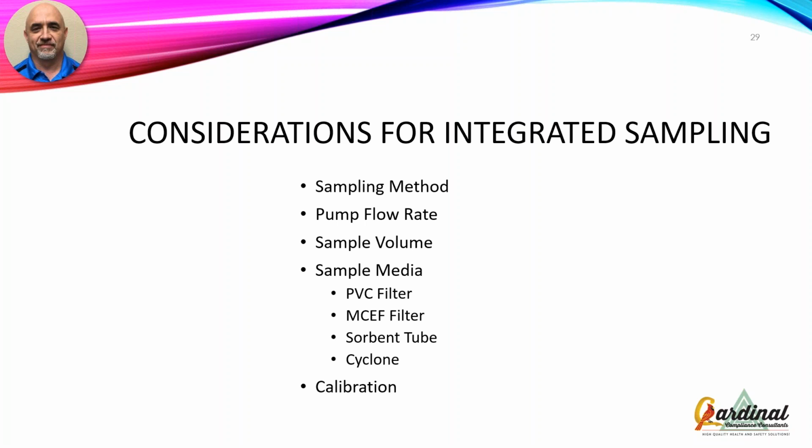Is the importance of that. Then I mentioned cyclone. Cyclone filters out the big pieces. We start getting into respirable versus non-respirable particulate, and then calibration. How do I calibrate? What do I use to calibrate? If I'm using a rotometer, has that rotometer been calibrated to a primary standard? A lot of different things go on there, and all of those need to be in play to make sure that I drive up my accuracy, okay?